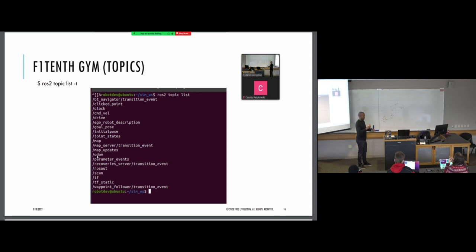It computes the delta P, or delta XYZ, from the velocity information, because velocity is P dot, the change in position over the change in time. But we're looking for position here, so it's doing a conversion, and that would be your odometry.